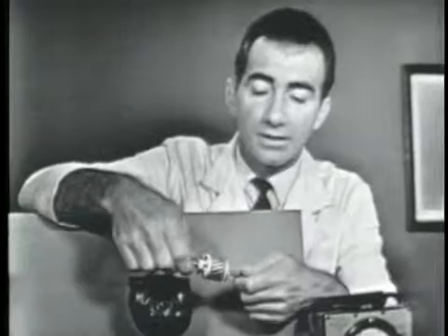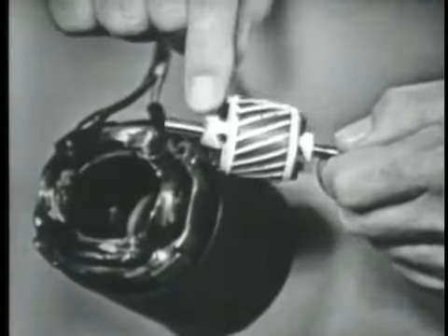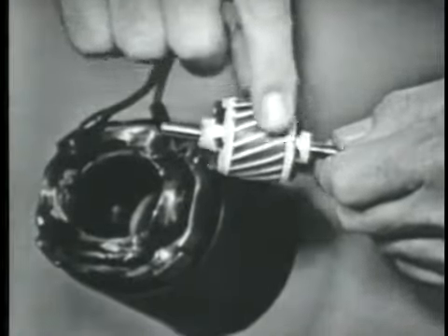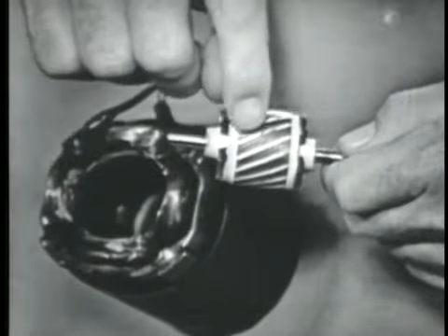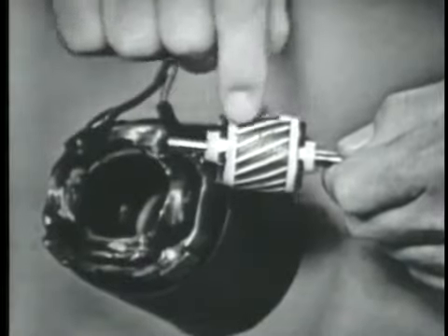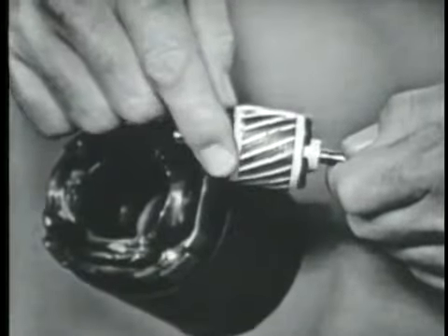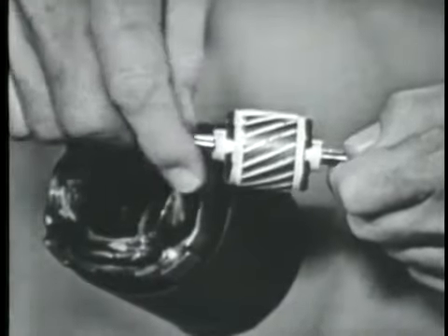Now actually, the rotor is the same thing, or almost the same thing. A rotor is made in a very, very similar way. Instead of using windings of wire, however, we use a conducting ring on this end, a conducting ring on this end, and they're joined together by conducting bars, these little white lines. Sometimes they're made of copper, sometimes aluminum. This one happens to be aluminum.